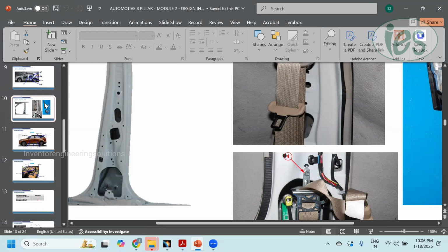From the dash, the main wirings will be passed through the pillars, and through this from the outside, the wiring harness will be passed through the doors. So this is the cutout for the wiring harness grommet. Each hole has a unique purpose. They are not simply added.